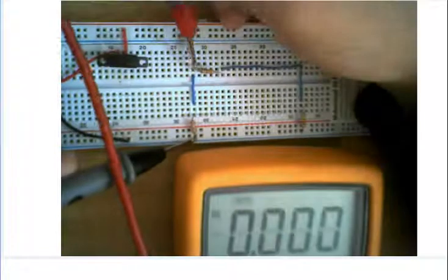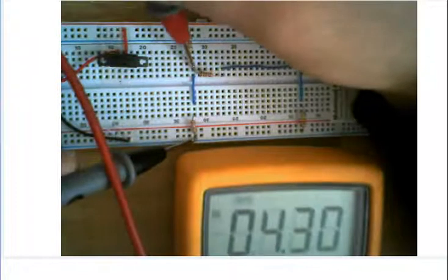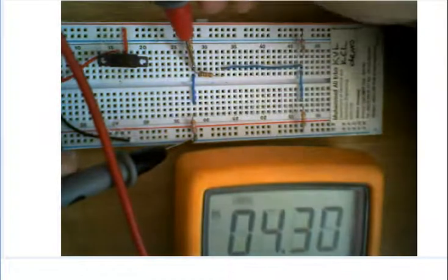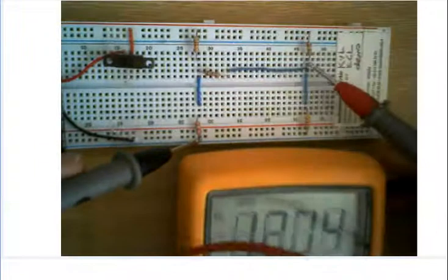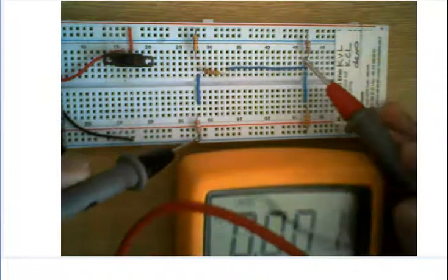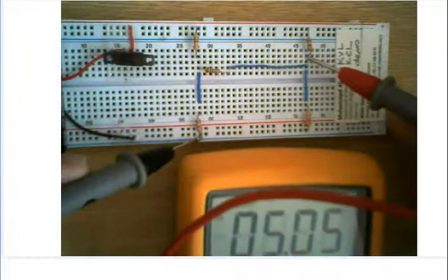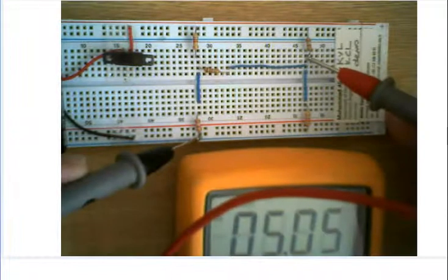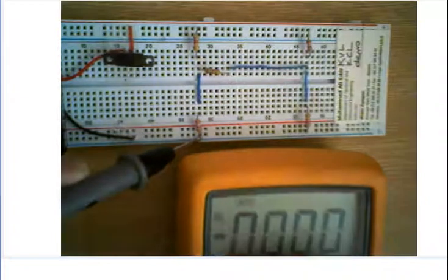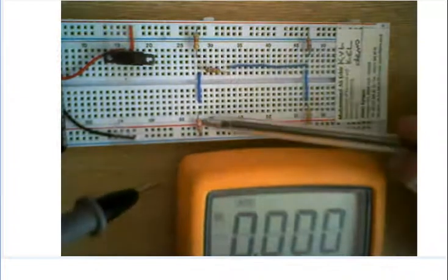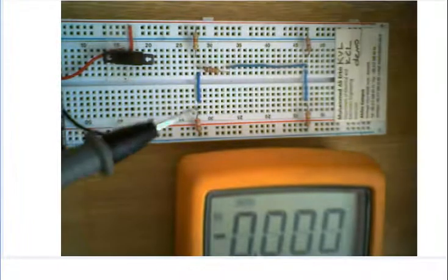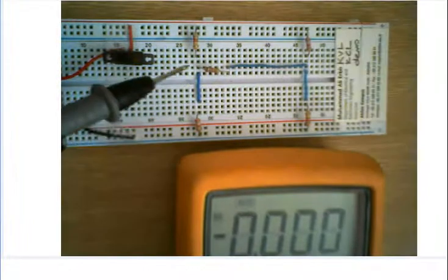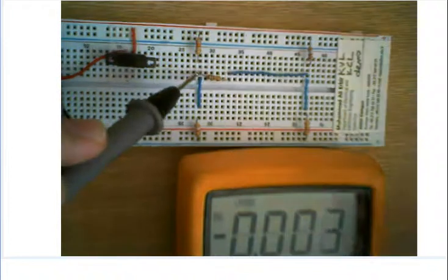And let's read the voltage of node 1, unknown node. As you see, it's 4.30, and the other unknown node voltage, I can read a voltage of 5.05, excuse me. So these are the node voltages if I accept this point as a ground. For example, if you assume this midpoint as a ground, then you have to touch the negative side of multimeter to this point and then read the node voltages.